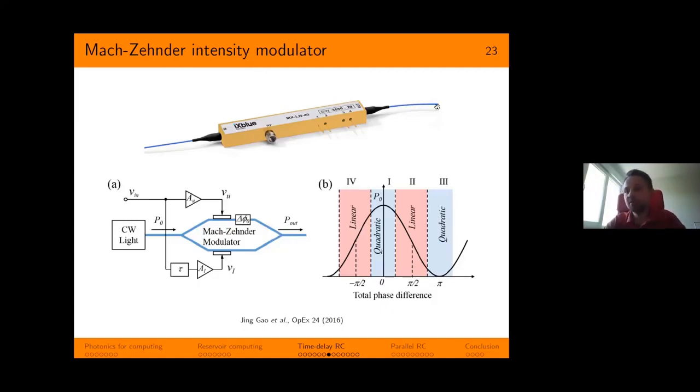And this modulation can be done very quickly, up to tens of gigahertz. Inside the optical modulator, typically made of a particular medium, which is lithium niobate, one finds an optical splitter like this, where the light goes either right or left. And then we apply electrodes either to both arms or just one of the arms. The electrodes allow us to induce a phase difference between the two arms, so that when the arms get recombined here, the phase difference results in a constructive or destructive interference, which acts on the amplitude at the output of the Mach-Zehnder.